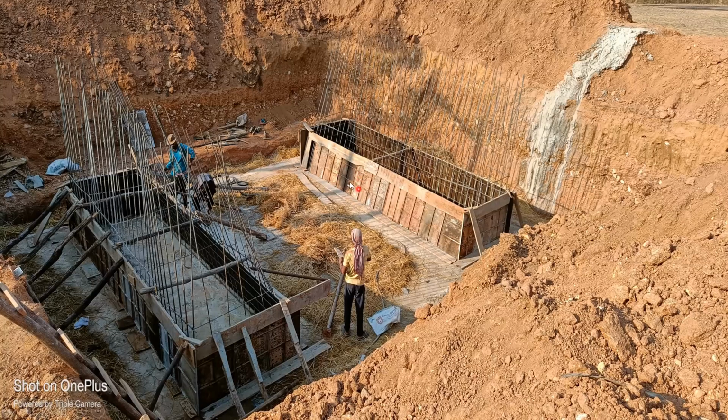We don't do that. We are going to do it in layers, one or two or three layers we are supposed to do. Again, the shuttering has been done. In this way, on both sides the shuttering will be done. This is a normal 10 diameter bar what they used here. Okay, 10 and 12 diameter. This is longitudinal. This is your horizontal binder what we have used. And then you're supposed to keep the cover block and all.